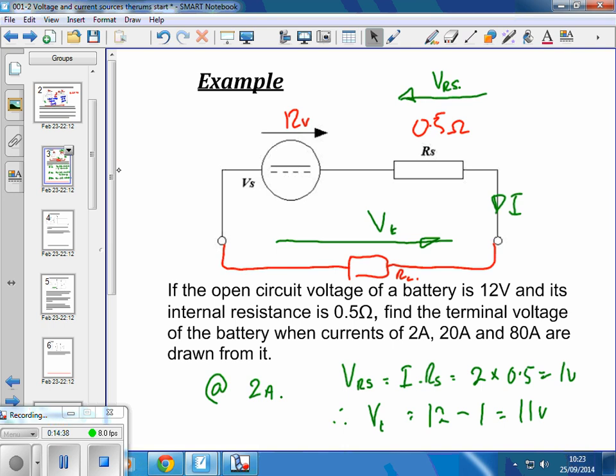And they can't change what the 3 variables are: the strength of the field, the speed that you cut the magnetic field, and the number of turns on the generator. Not too much chance of changing the number of turns on the stator while it's running. Can't change the speed because the frequency will change.